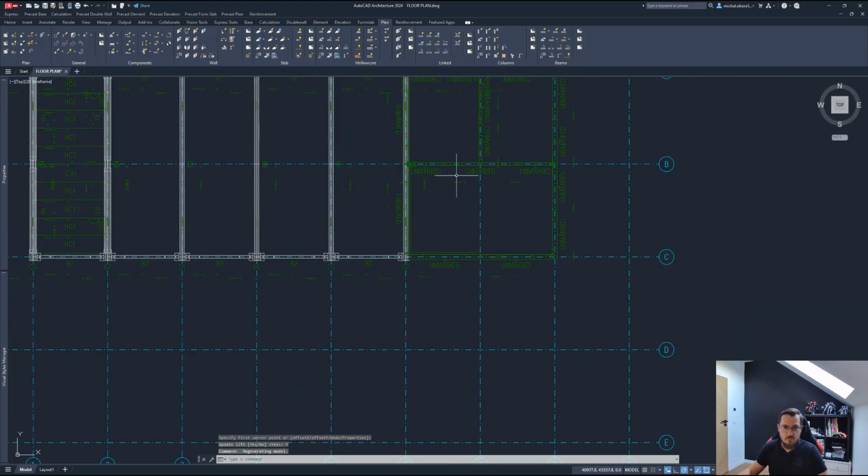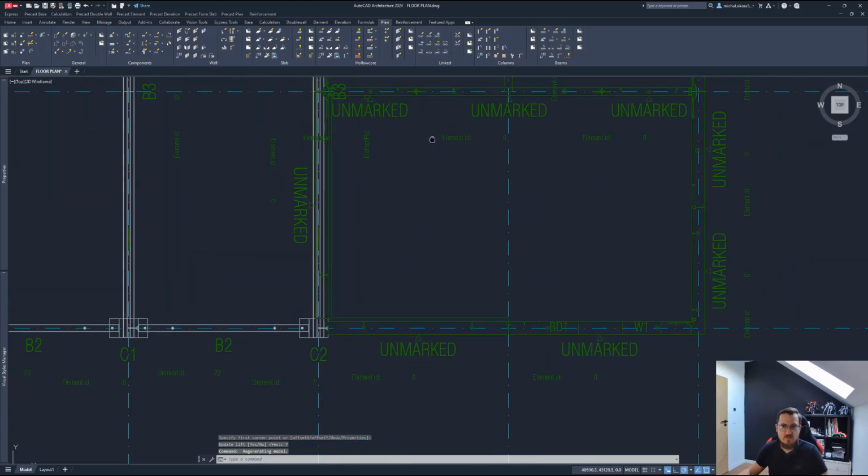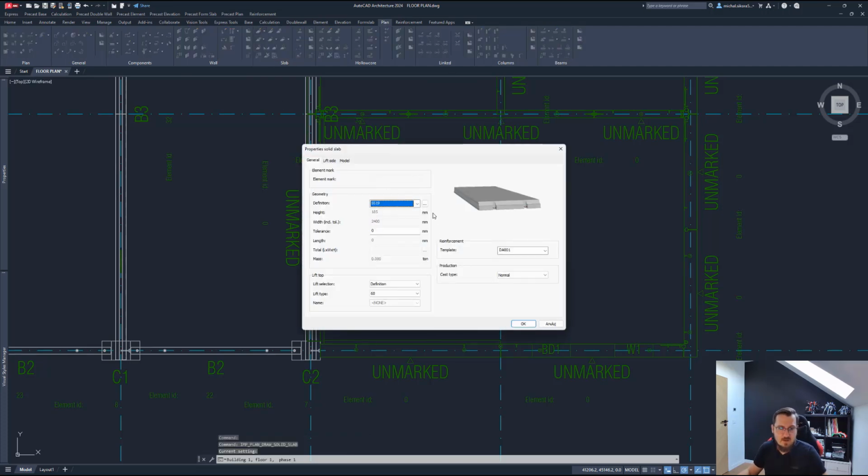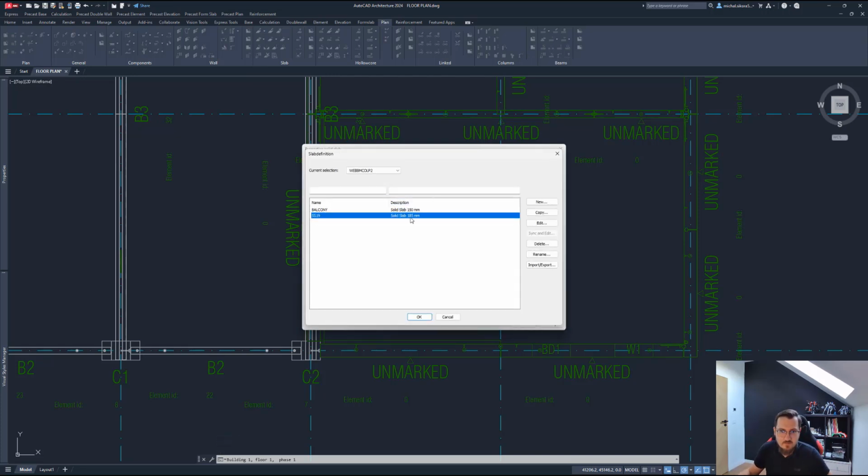Because now with panel thickenings, I'll show you later how to add reinforcement to that on the drawing, but now let's actually place some slabs for us. So slabs, very simple. We have an icon for those. It's again a bunch of settings that you can have. Definition, I just have one type of slab defined here, a 185 mil tall slab. That's it. And also 150 mil balconies.